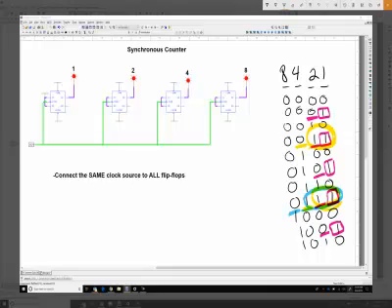It's kind of like counting in base 10, or in regular numbers. The next place value counts up when all the previous place values are already at 9, as in 999. So if all the previous bits are full, the next place value should count forward. So that's what we want to do. We want to check when the previous bit is a 1, and then we enable the next flip-flop to be ready to toggle.